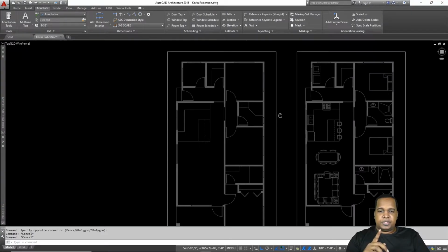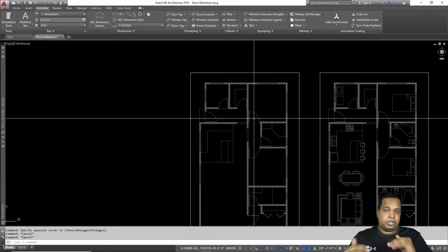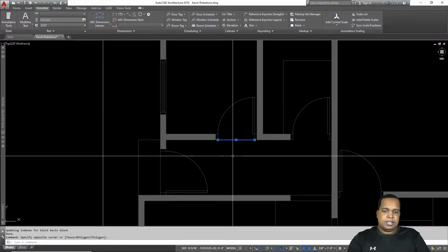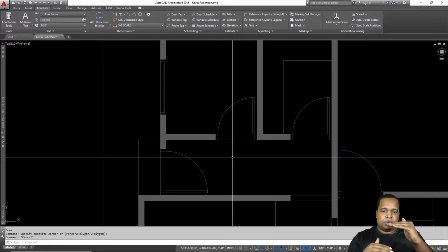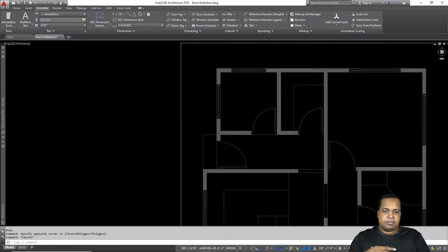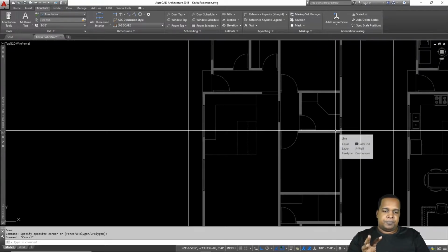What we'd also need to do is create separating lines, because when Photoshop applies a filter layer, it would fill the entire thing, and we want lines that would separate different components. So let's say here would be the laundry room. We need to put in this line to say that the laundry room tile would be separate from the corridor wood flooring. So when we go into Photoshop, this would be one element and this would be an element by itself. So you would need to take the time and go in based on your drawings and create these lines where needed.